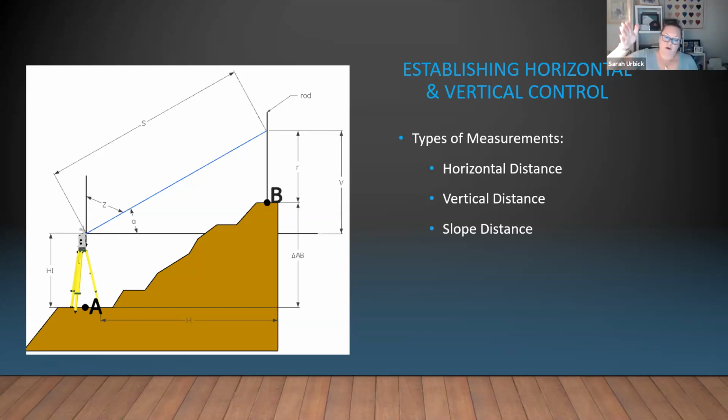When I go out and I have to cover that with a foot of fiber mulch, I need to know that value. That's going to make a big difference if we're talking dollars, right? So that's why we want to know what that slope distance is going to be. It's one thing if it's flat, it's another if it's angled, right? So that's why we drive home the trig review.